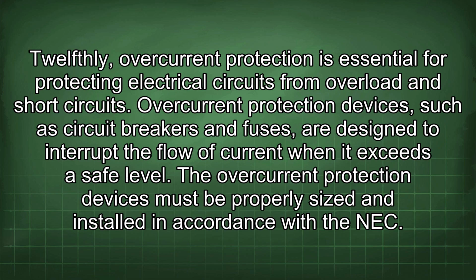Twelfthly, overcurrent protection is essential for protecting electrical circuits from overload and short circuits. Overcurrent protection devices, such as circuit breakers and fuses, are designed to interrupt the flow of current when it exceeds a safe level. The overcurrent protection devices must be properly sized and installed in accordance with the NEC.